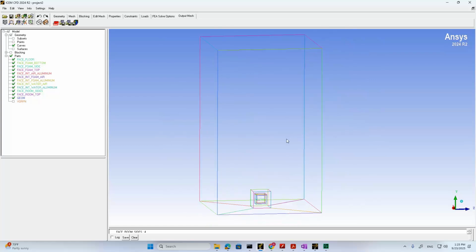So when we do simulations in Fluent, we always have to at least provide three things to Fluent. First, mesh, as I have just mentioned, right? Wherever you need data, you want Fluent to solve for results, you need to create a mesh at such places. This is the first thing you have to give to Fluent, right? Mesh.